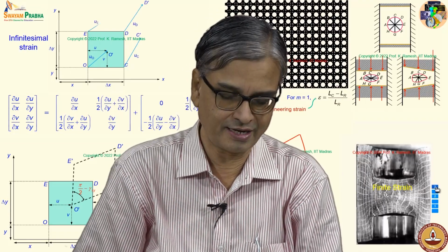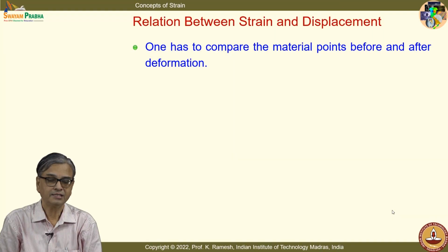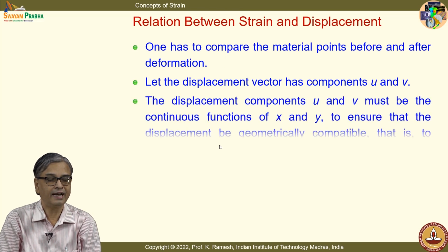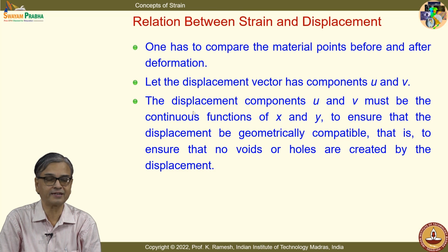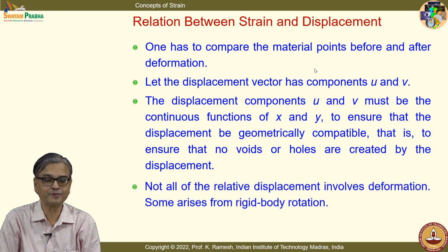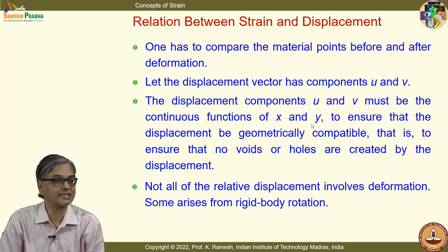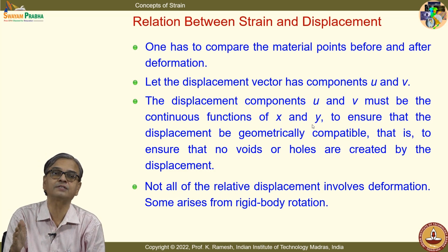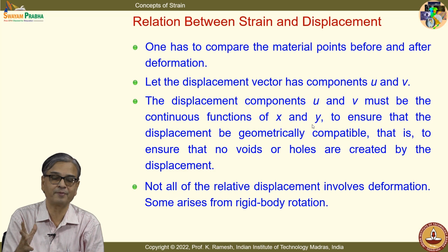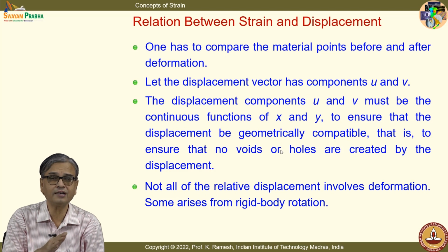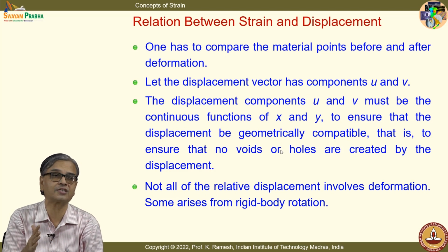We will also look at it from a displacement perspective. See, we have to look at what happens before deformation and after deformation, and let that be dictated by a displacement vector. When we look at a planar situation, it has components u and v. And how should the displacement components be? They should be continuous functions of x and y, so that when the material deforms, I do not have voids, I do not have separation, I have compatibility in the deformation, all that is taken care of. And you will also have to look at the fact that it is not always the relative displacement that causes strain.